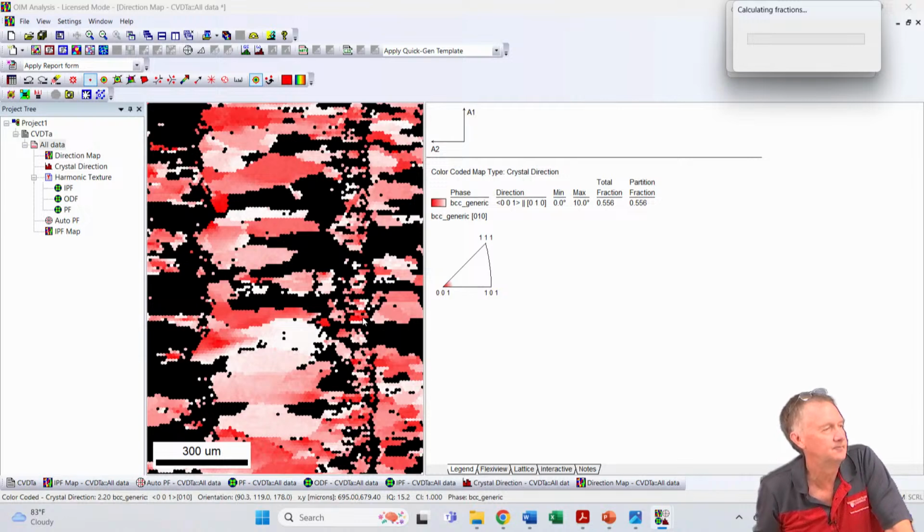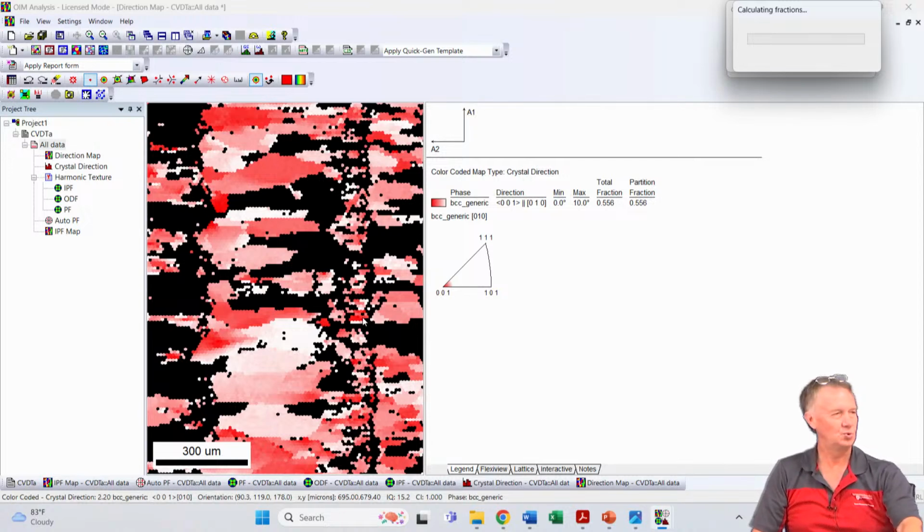The brass component is 110 aligned with this 001? For brass it is 110, 112. What? 110, 112. 110, 001 is the Goss component. Yeah, so brass is 110, 112. Okay. Others? Okay. We'll try it again tomorrow.